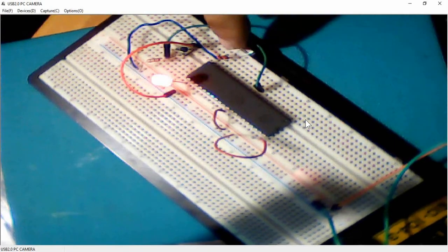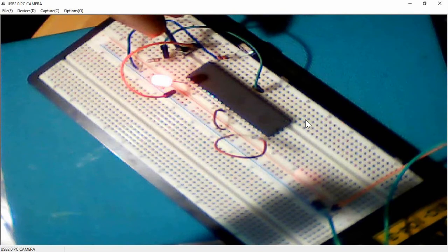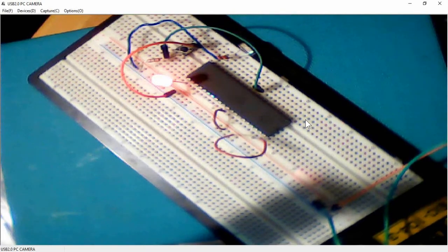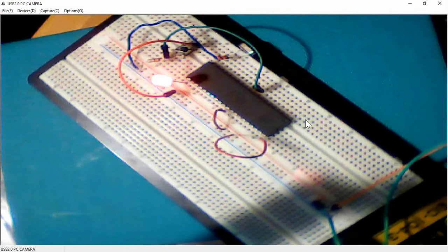The reset, I'm using it without a capacitor, but it's working, so it's better to use a capacitor. Okay, and ground it through a switch. The LED I can connect to any pin on port 2, and because I have the entire port 2 on, it's blinking. Okay. So that's how we program a microcontroller using the miniPro programmer.